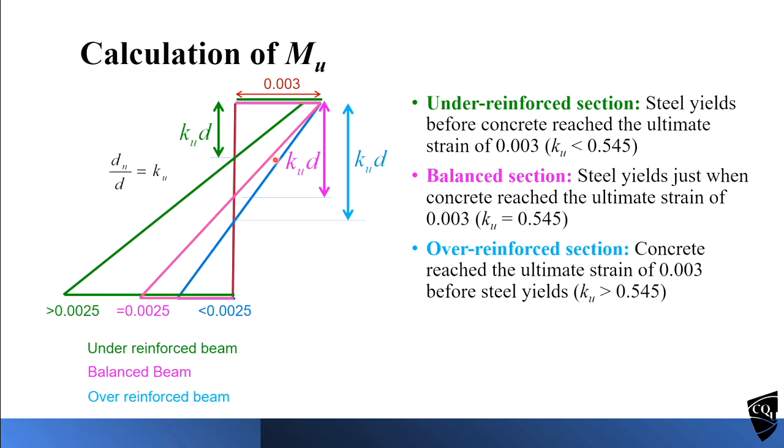Before 2009, the ductility requirement was used as 0.4. And at that time mostly we used Y-type bars, not N-type. Y-type bars have a yielding strength of 400 MPa. Now we have 500 MPa. So that's slightly different, so the standard was revised.